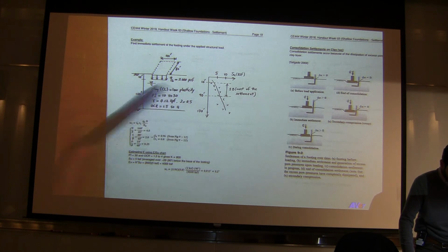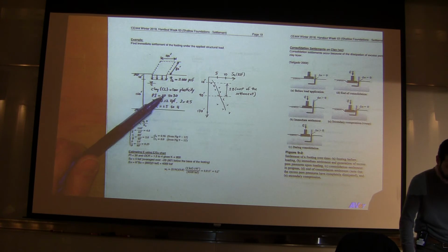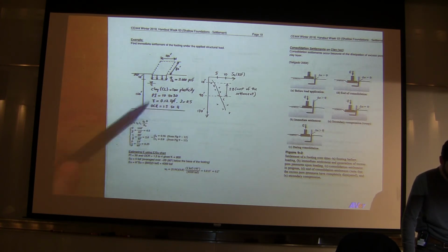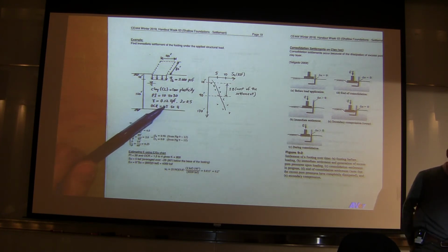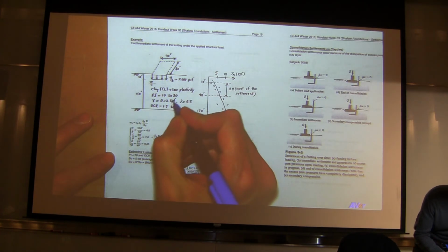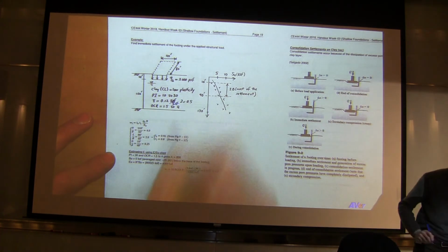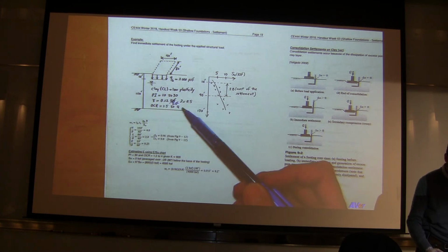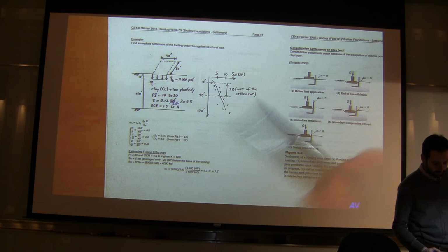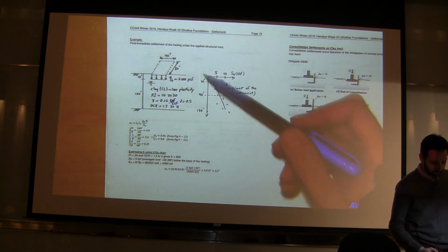Some parameters of the clay are given, it's a clay CL. What is CL? I have it written here. Low plasticity clay, right? PI ranges 10 to 30. Gamma is 120 PCF or 0.12 KCF. Poisson's ratio is 0.5, OCR is 1.5. And the SU is given here, so it increases with depth.